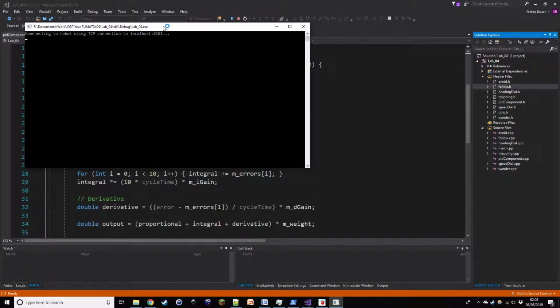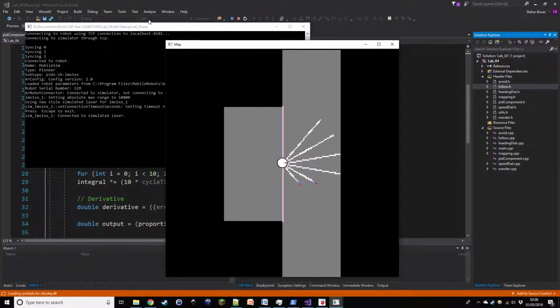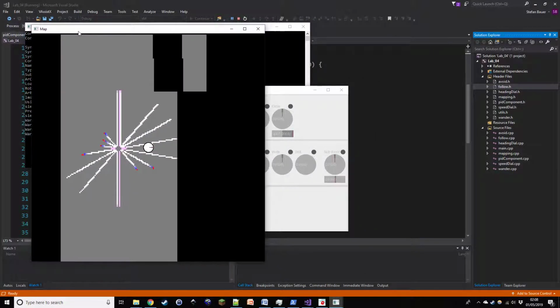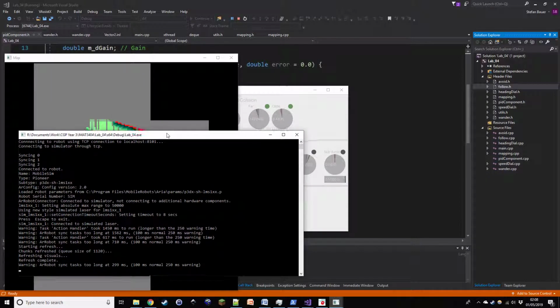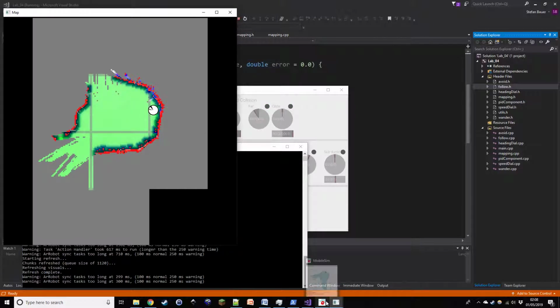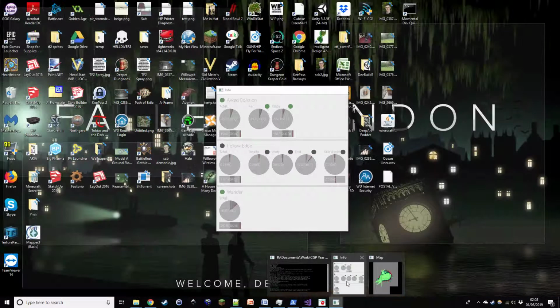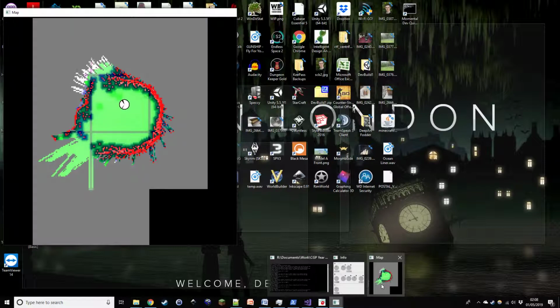Now, the wander and mapping behavior. This makes use of a kind of flow field, almost, where every map tile has a traversal cost dependent on how full it is or how close it is to a wall. So filled obstacle pixels impose additional cost on nearby pixels dependent on how close they are.